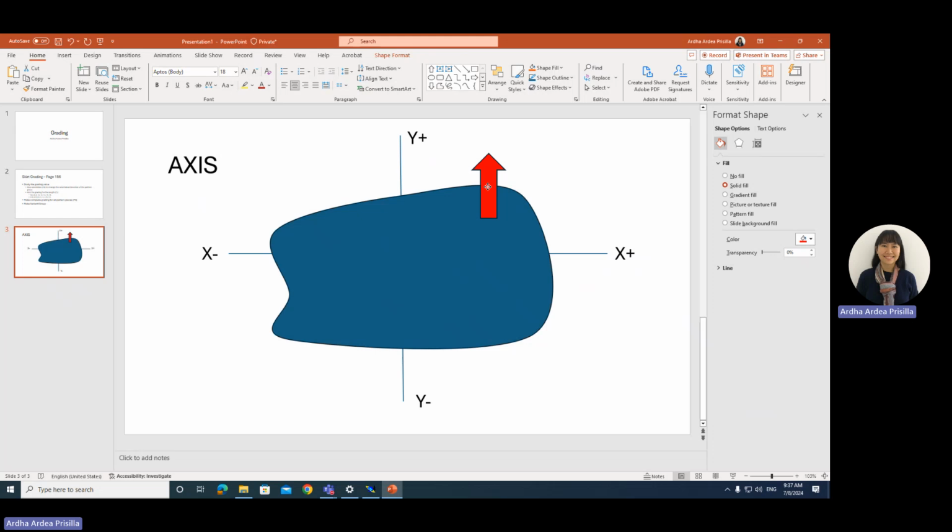In your book, you can see different values. Some values are positive, some values are negative. You can see in the book, page 156. However, in Lectra Modaris, you don't need to differentiate the value. You need to check the direction. If the direction of the grading from the smallest size to the biggest size is going to the right, that makes all the values in your grading positive.